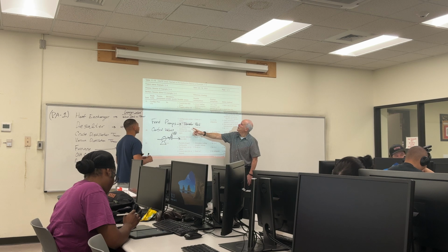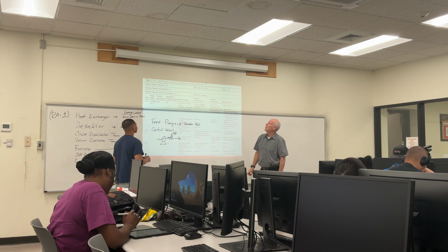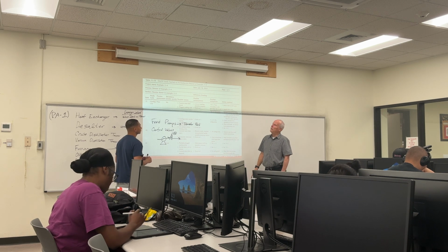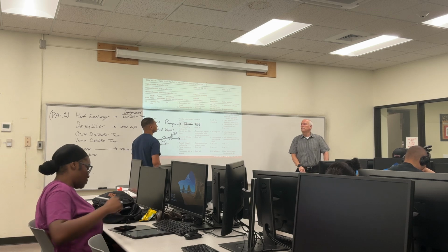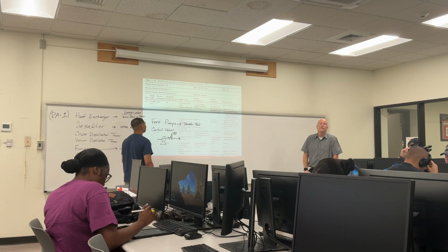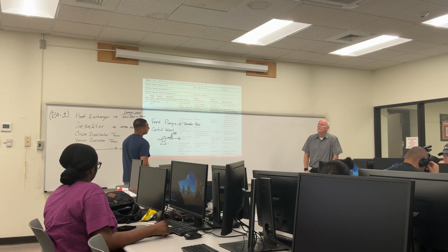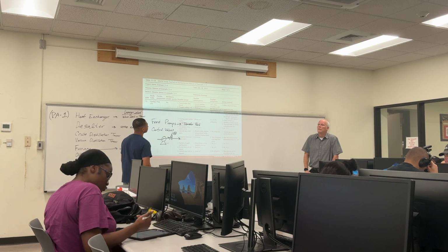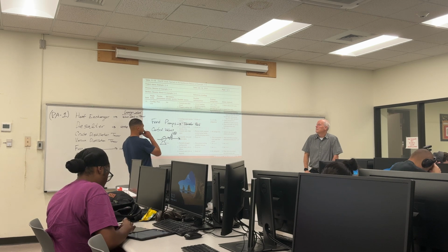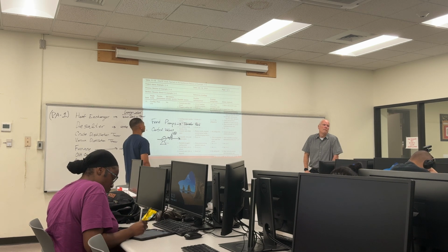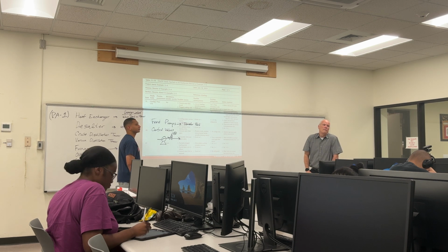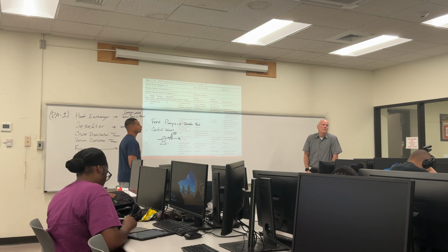Then it comes back to, what are your scenarios that cause this to happen? What's a scenario that would cause this, loss of design intent of the feed pumps to transfer feed? What's a scenario? Something happened upstream, like maybe there's a pipeline rupture upstream, like there's no flow going, or the valve fails closed. Pump shuts off, pump motor goes bad on the pump. You got a lot of them, right?